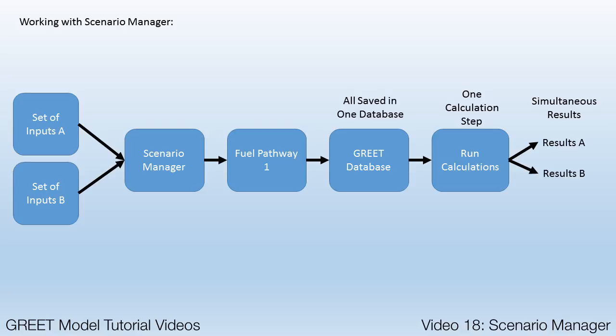With GREET 2016, the Scenario Manager allows a user to save and manage multiple sets of inputs or parameters for any pathway without the creation of new pathways or management of multiple GREET database files. This tool records changes to values, but doesn't alter the model structure, so users can test various fuel mixes for the same pathway or track regional variations to measure the emissions impact between locations without creating alternate versions of GREET. Scenario results features allow comparison of multiple scenarios easily and quickly.